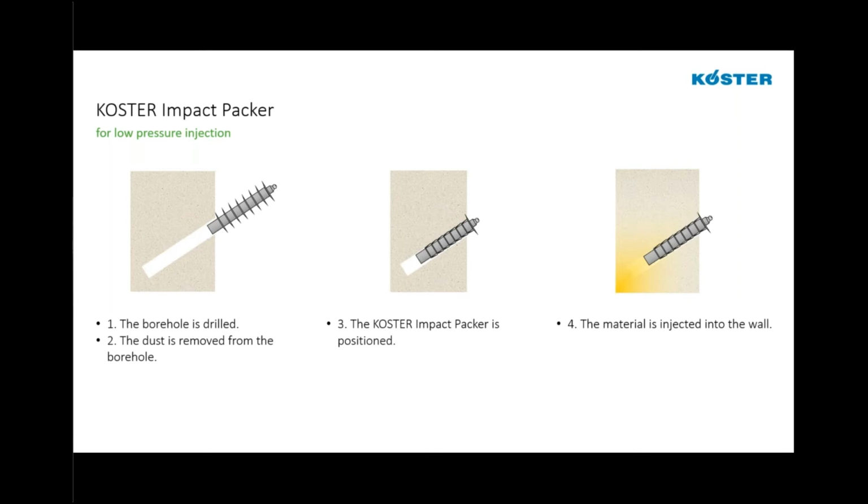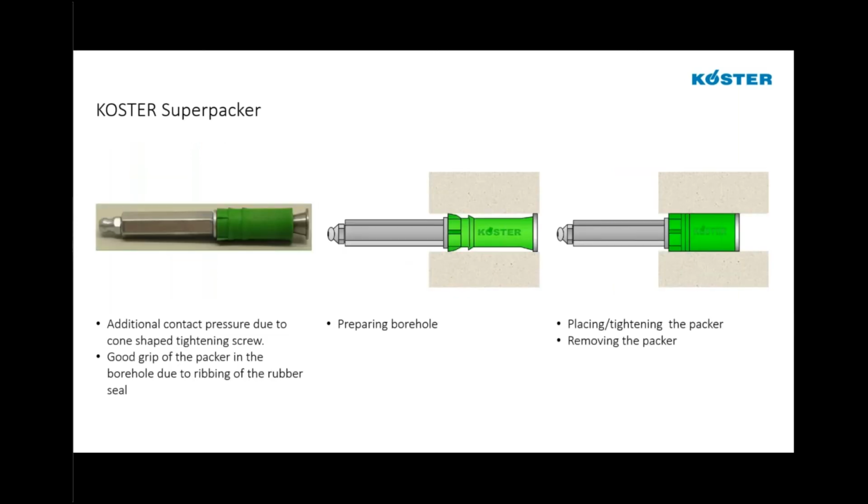deal with something with a little more ability to attach itself to that borehole, so that we don't end up getting an increase in pressure in that packer potentially blowing out of the borehole. Like any, obviously, safe injection works. When we're injecting into any of these ports with any kind of pump, we never want to stand directly behind the packer in case we do get a blowout of the packer. That's just your typical safety measures.